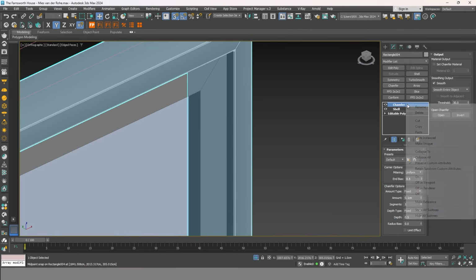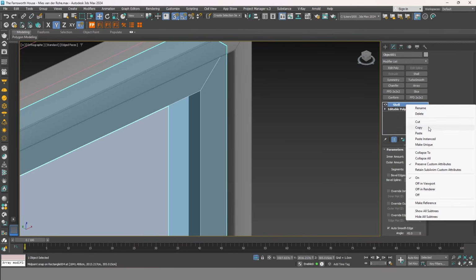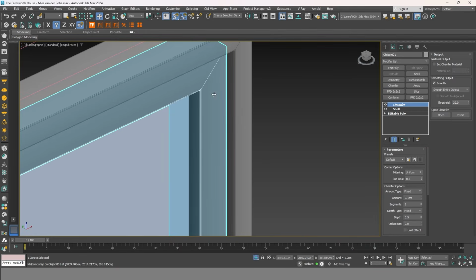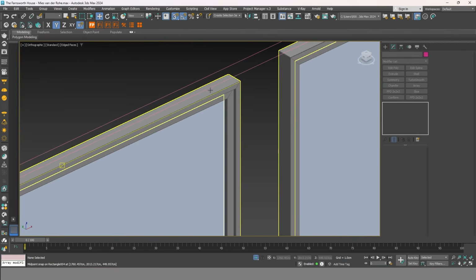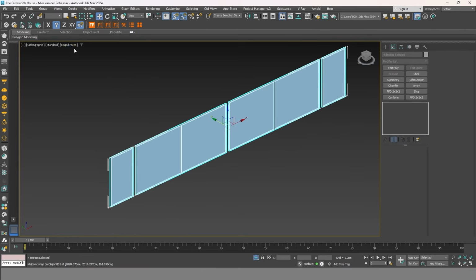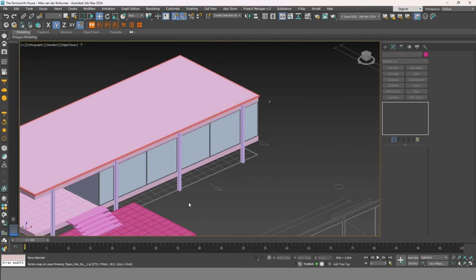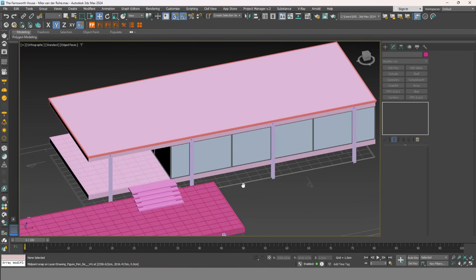And again, you just need to copy it, and this time paste it as an instanced modifier. And of course, from the options here, make sure the smooth chamfers only is chosen to keep the other surfaces flat. So, group, close, and isolate, and then you need to go and paste it for all the other frames.